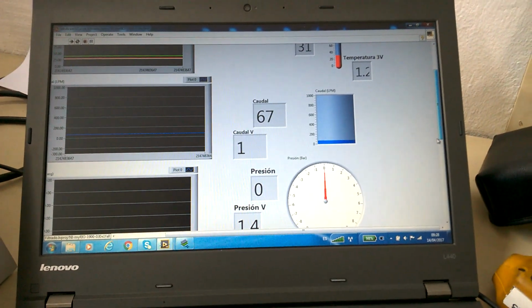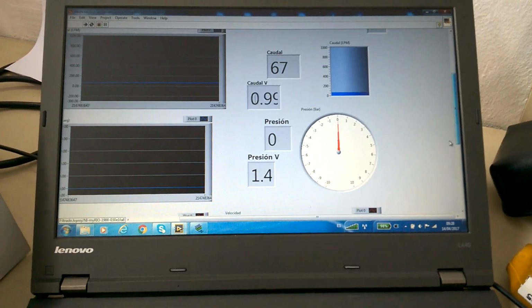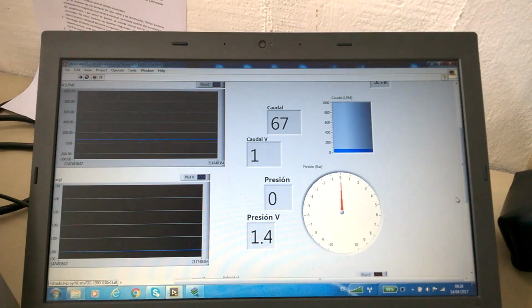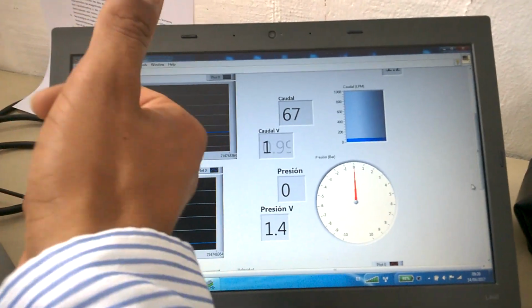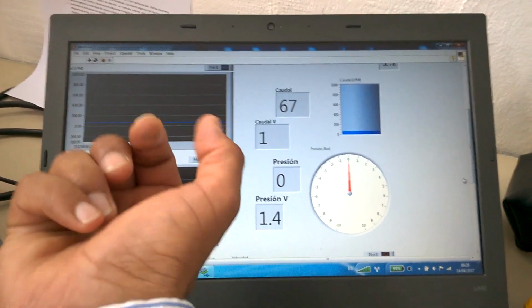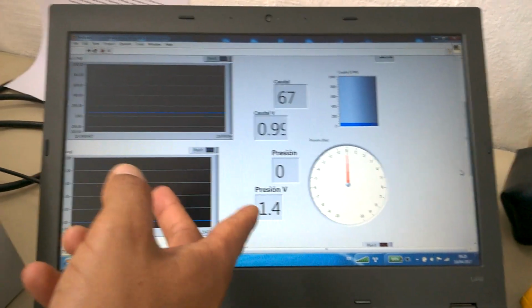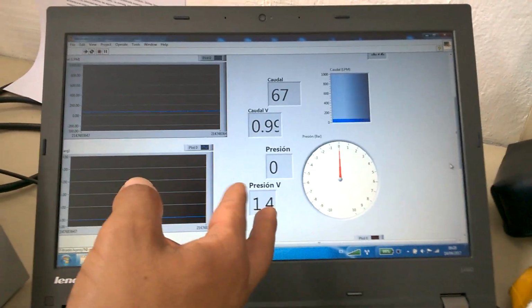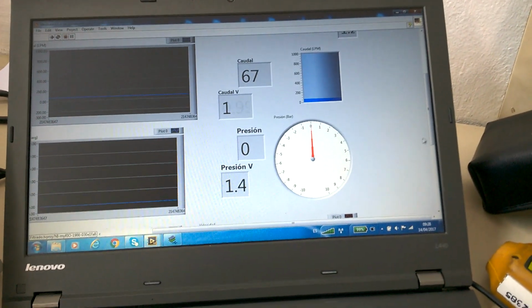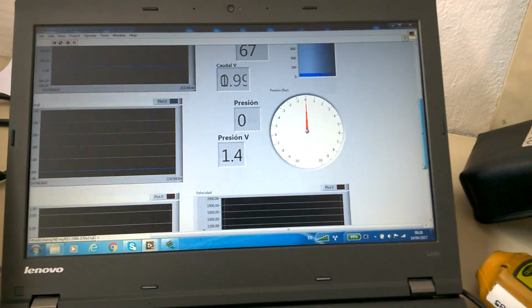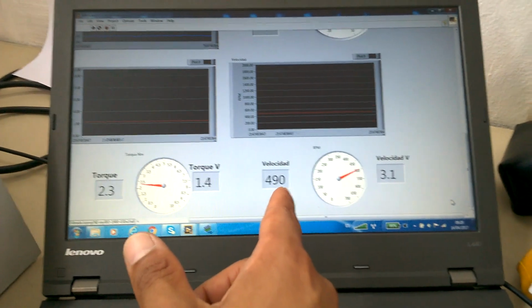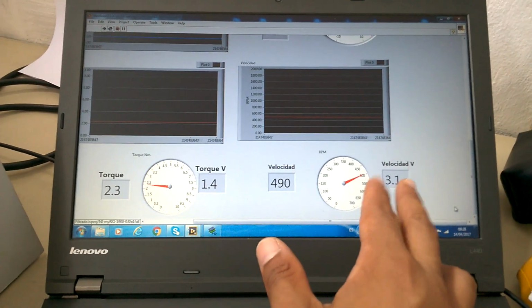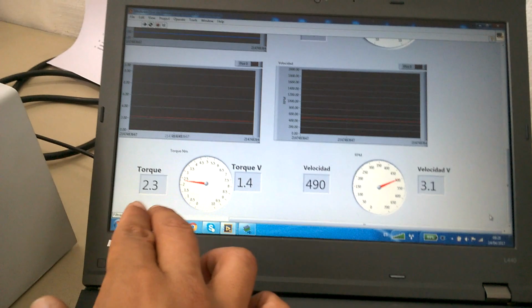liters per minute, and the pressure has an equivalent voltage, because the sensor has an equivalent voltage, which is transmitted and calculated in physical parameters for flow. The same goes for the pressure sensor, from voltage value to pressure units, in bars. And finally, the speed of the compressor, 500 RPM more or less from this sensor value, and torque in newton meters. Well, where is the trouble?